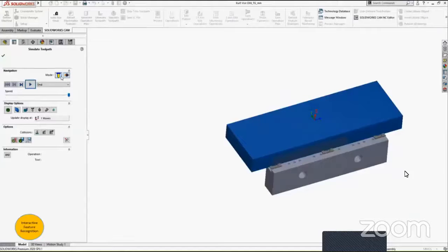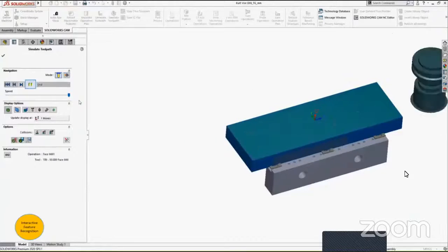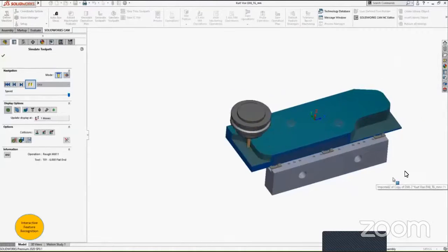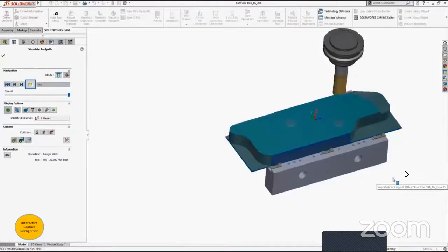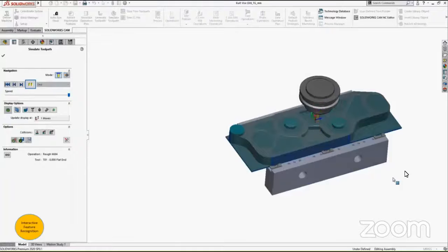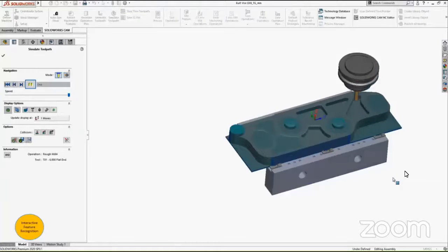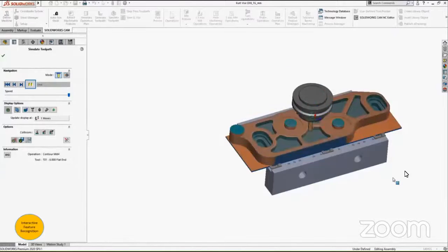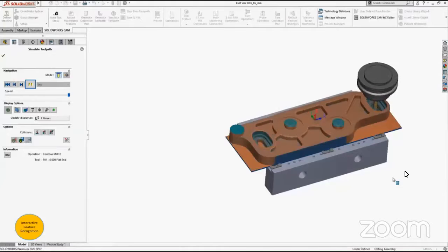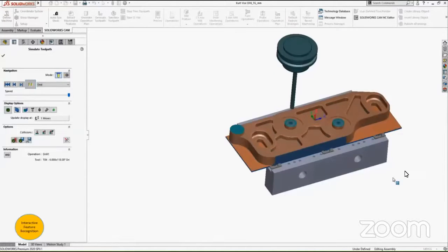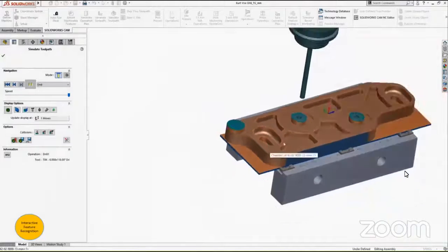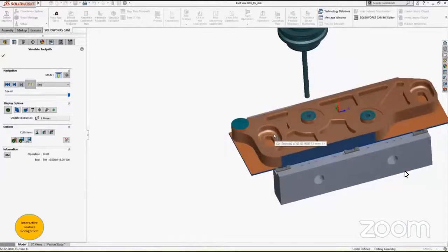turbo mode method. So let's see the simulation. So the perimeter operation is being performed here, removing the material from the outside. Now the roughing operation, pocketing. Yeah, now the contouring has been started as it shows in the orange color. We have a pocketing, and now it's creating a pocket, and there we go, where we can zoom and see the round fillet. Since we are using the ball nose type of tool, when it performs the machining, it will create this type of fillet.